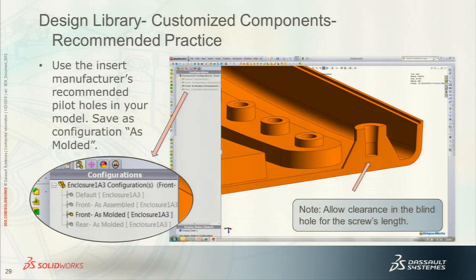And here is one suggested approach on modeling your parts where you are using ultrasonic inserts. You should incorporate the pilot hole that the data sheet on each individual insert recommends. You can create a configuration in your model, call it as molded here.